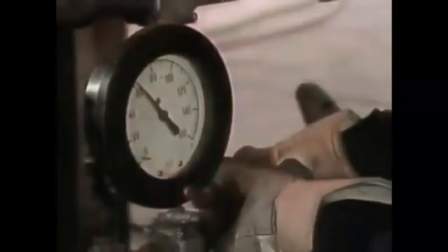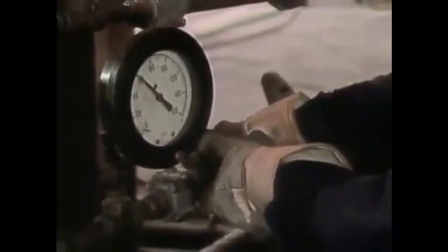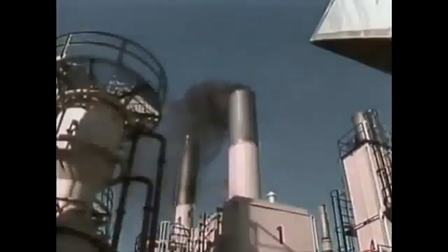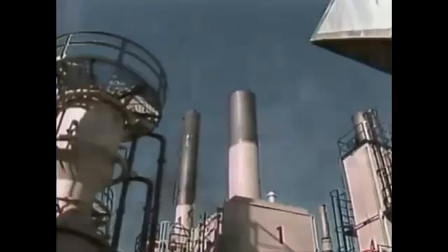The fuel oil pressure to the burner can also be adjusted. If the fuel pressure is too high for the amount of atomizing steam and combustion air that's supplied, the result could be unburned fuel oil. This shows up as a smoky, hazy firebox and smoke coming from the stack. This problem is typically corrected by decreasing fuel oil pressure or increasing steam or air to the atomizer.